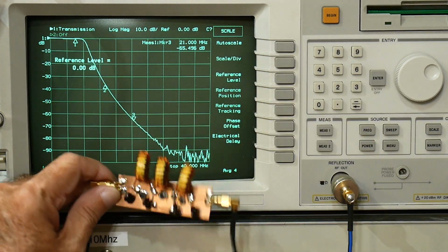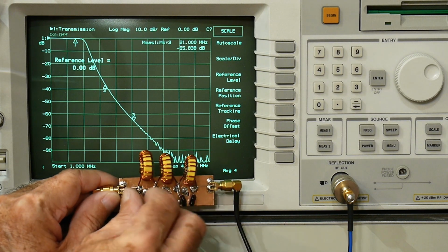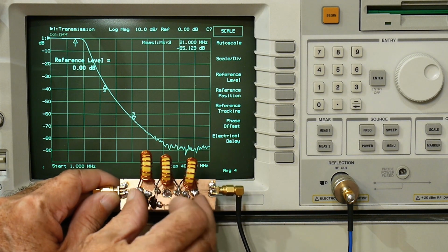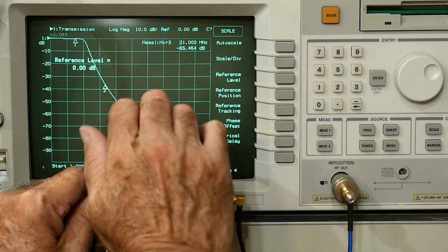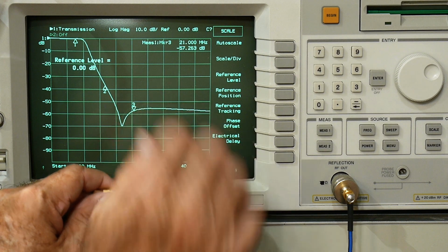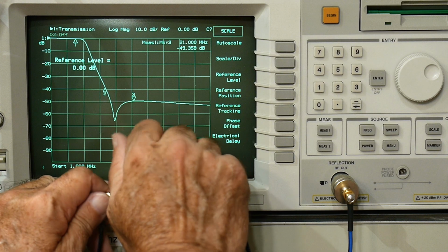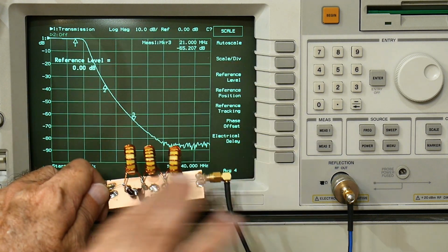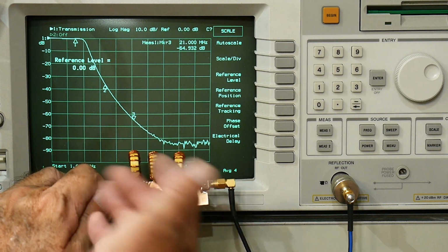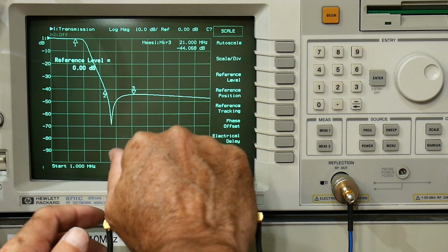There we go. And so this idea of having capacitors closer together, you see there it's going up when I have these capacitors close together, right? If I put my fingers on it, they come up. If I put my hand around it and then couple the signal across from one section to the other, you see that the rejection, now there's a path around the filter, right? There's a way for the electrons to get around. They're going through my hand, right? Instead of going through the filter, they're going through my hand.